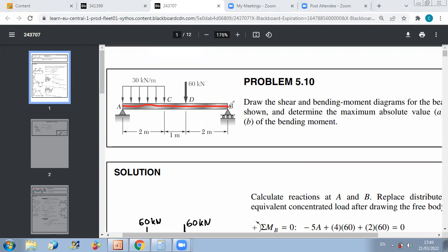And of course, since transverse load will also create shear forces, shear stresses, then we should determine the location of maximum shear. And then this will help us in designing the beam, because we'll make sure that the material of the beam can support both the maximum bending moment and the maximum shear applied. So always in such problems, the strategy will be to first get the external reactions, because whenever I want to do a cut, I should know the external reactions to be able to calculate the internal reactions developed.